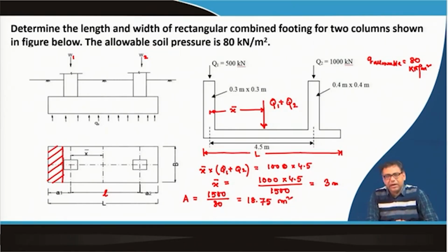It is the allowable bearing pressure. So that means settlement and bearing both are considered, and the minimum one is given as the allowable bearing pressure. Last class I discussed that you can go separately and provide the minimum one, and there is a correlation also available where you can directly get the allowable bearing pressure. But in the previous case we saw that the settlement consideration gives the lowest value. That is why you provided that. So here that value is directly given.